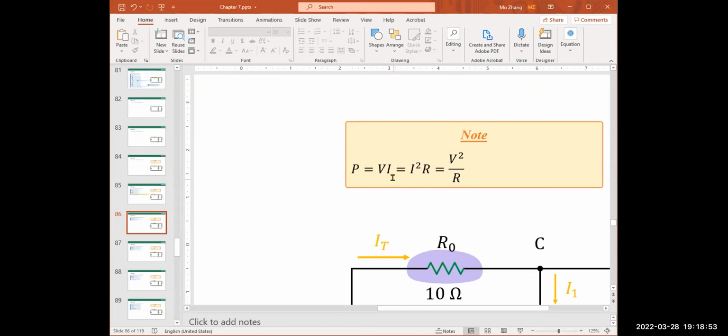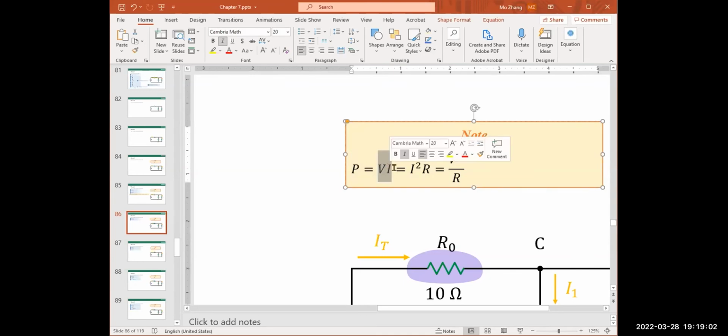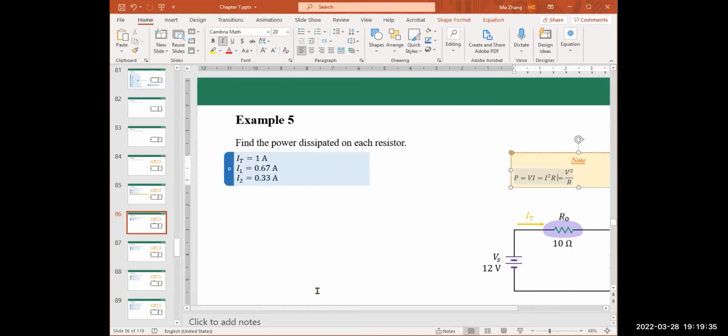And we actually did this in class. We use the Ohm's law formulas, combined with the definition of electric power, and derive 2 more forms. Let's say if we only know current and resistance, we still can find the electric power. So electric power P is the current squared, I squared times R. And if we don't know current, however, we know voltage and resistance, we still can find the power in one shot. That's voltage squared divided by resistance. Those are the 3 formulas.